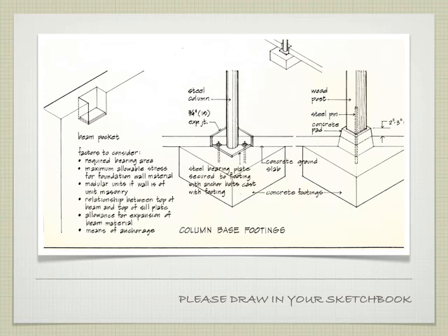In this particular case, we're embedding the steel all the way down to the footing. We're using 2 anchor bolts to anchor that column to the footing itself. These little anchor bolts would be embedded in the concrete when it was poured, and then the column would be added later. There's a bit of an expansion joint, and then this is filled inside with a grout, or basically concrete, to make up the floor, right?